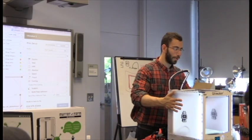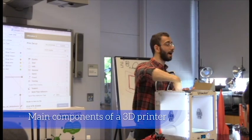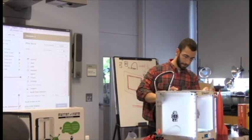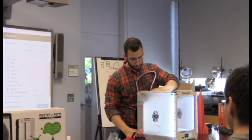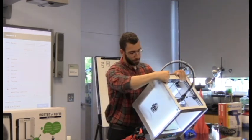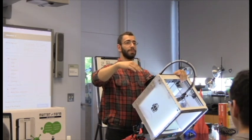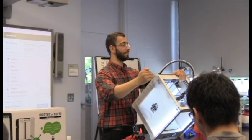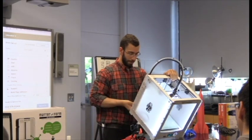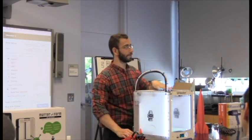Okay. The main components of a 3D printer that you're always going to be dealing with is the hot end. The hot end is this guy over here. You see how this guy moves here on the top? I can move this along my y-axis, my x-axis. Different printers work differently. Sometimes the actual head goes up and down, as in the z-axis. In this printer, what happens is that the bed goes up and down with a threaded screw. You have one threaded screw, and as this turns, it brings the bed up and down.